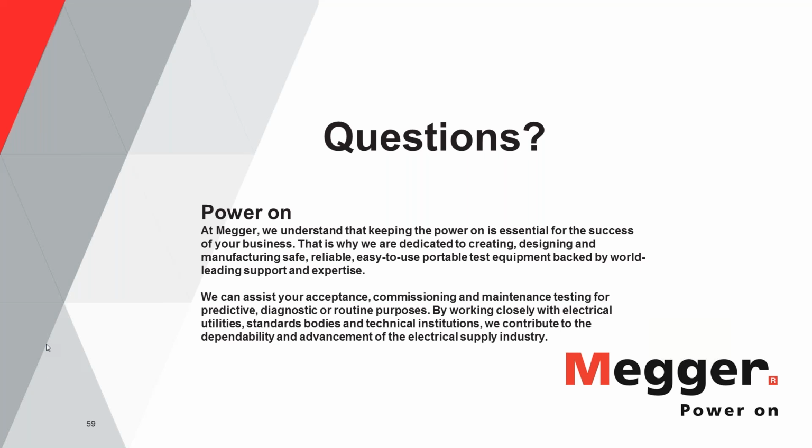All right. Our next question is, how are cables from the test set connected to the circuit breaker when the circuit breaker is installed? As shown in the presentation, connecting to the circuit breaker is one of the key points of the test. If you don't have a good connection, you will have a high impedance, and that will make your test difficult, or you're not going to be able to test it. So you have to have short cables, and a very good, tight connection.